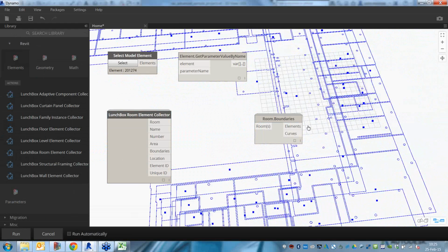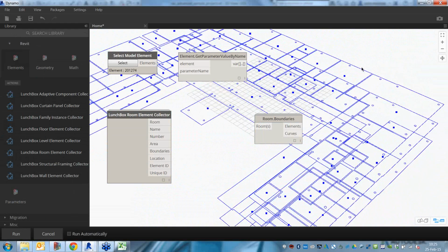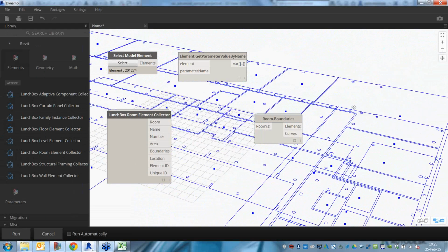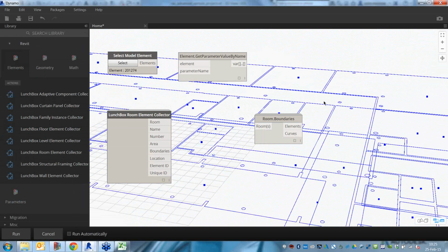Inside of Revit, there's a bunch of rules for different types of area layout already, but they're kind of hard-coded. So if you wanted to build your own rules like that, there are ways to do that. You would need to know the thickness of the walls. You would need to control not just the location line of the wall, but the placement position, basically, is the wall centered on the location line, or is it offset to face of interior, face of exterior?